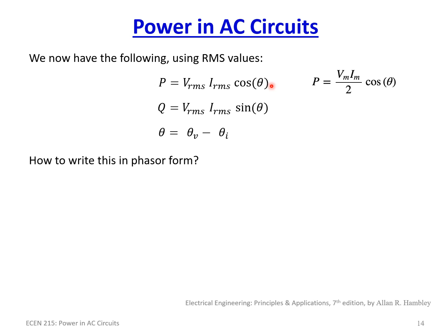So how do we write this in phasor form? Everything we've been working with is mostly in phasors, and it would be really useful to go ahead and compute power using the phasors straight out. Naturally, we would just say power is equal to V phasor times I phasor, bold V times bold I. But that's not how it works out.